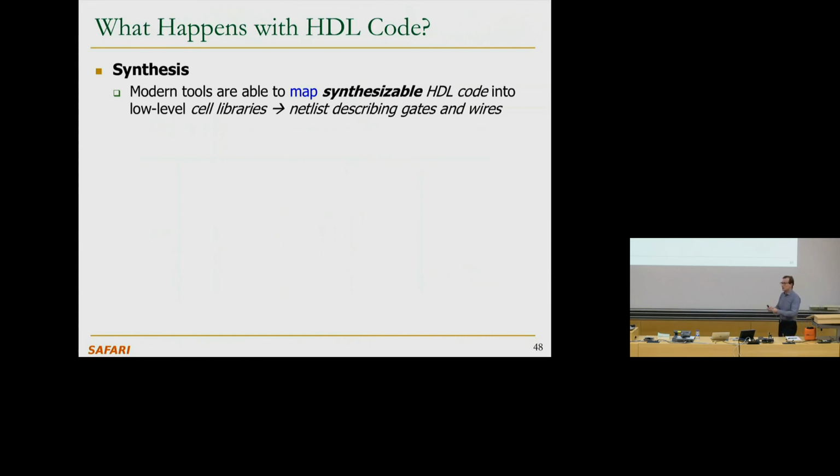Structural Verilog, you can clearly define your circuit at almost the lowest level. So these synthesis tools can also perform many optimizations. If you, for example, have a multiplexer that's designed using the ternary operator, remember the question mark and then the colon, then it can actually give you a multiplexer that's really fast.